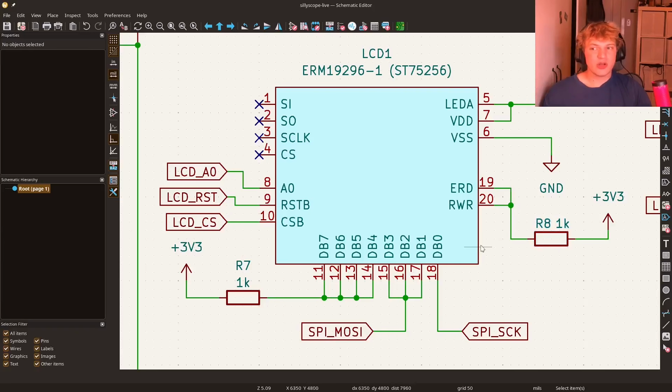I just want to add a quick note about sharing pull-up resistors. You'll notice these signals here and these signals here are sharing pull-up resistors with each other. Now this is fine because they are unused. Essentially the guide just says, since they're unused, you should pull them up. So that's what we're doing. In this case, it is perfectly fine for them to share pull-up resistors. If they were constantly changing or they needed to be at opposite polarities, this is probably not going to be a good idea, but because these are static, having them share the pull-up resistor is perfectly acceptable.